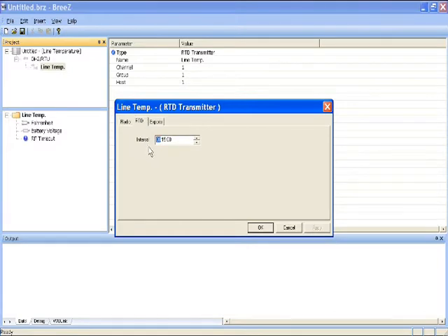Here is the reporting interval that you will ask the sensor to report to the DH2. We will set this for 1 minute today. Return to the Radio tab and put our node timeout at 4 times greater than our reporting interval, and then move to the Exports tab.